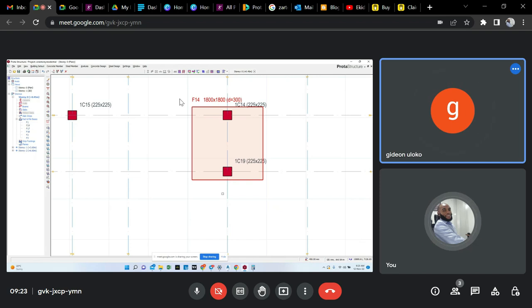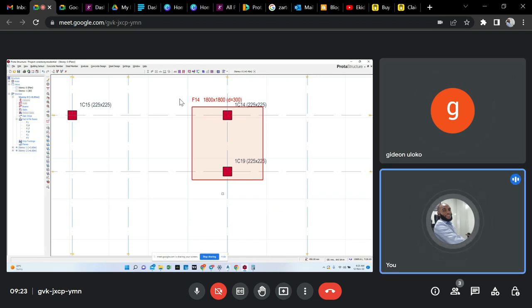But this alone right now is okay. But if you think maybe someone will go and question you on site, why is the column very, very close to the edge of the footing? Just to avoid those questions, either you make it a rectangular footing individually, or a combined footing and then increase to at least 2.0, just to avoid that kind of question on site. You understand? Okay, so let's see the 3D view of what we have done.